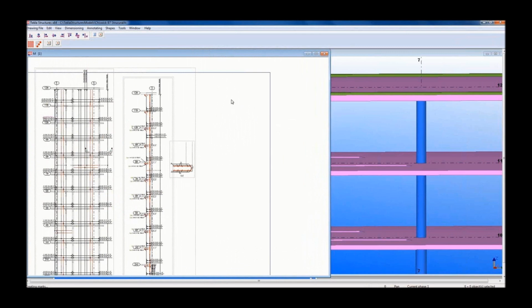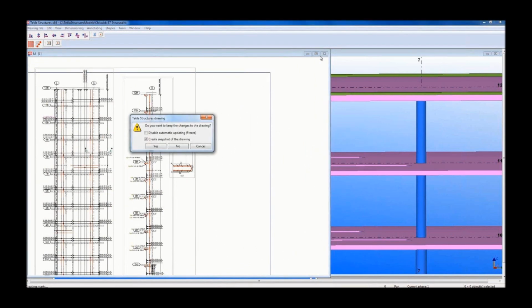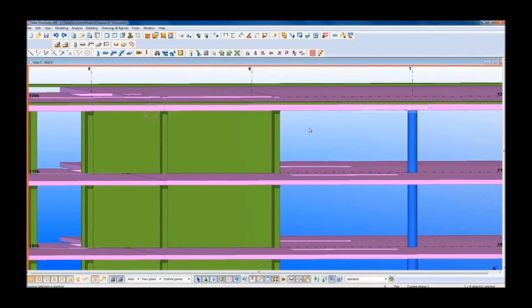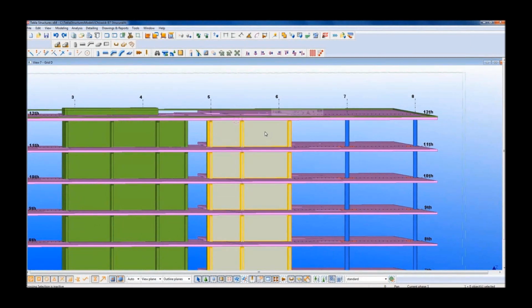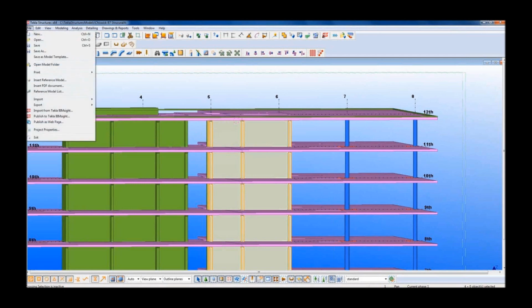We did say we're going to go on to digital scheduling as well as the traditional scheduling. So if I close this drawing down now, and I go to, basically it really does look after itself. So if I pick this, as well as saying that you can create the traditional schedules from the model to British standard for the engineer to check, what we can also do is export to a few CNC type things, so BVBS export for bar bending machinery.